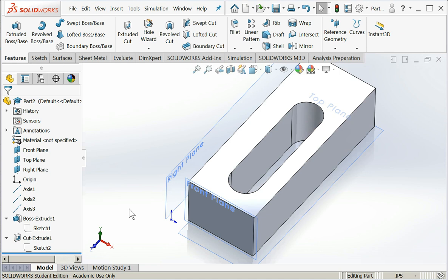They're easier to constrain. If you have a sketch that only has, say, 4 or 5 lines, that's very easy to constrain. If you make a complicated sketch with a lot of lines, they're hard to constrain. Sometimes the computer will resolve the sketch badly and they can blow up into a spaghetti mess. So small, simple steps is in your best interest.